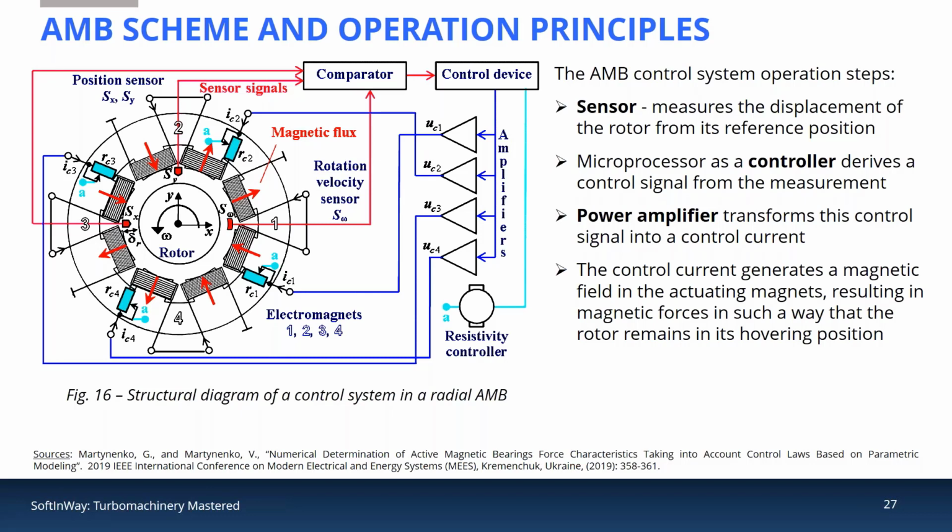The adequate variation of electromagnetic field requires using a certain control law. The control law should be designed properly and ensured by the control system. Magnetic suspension can include permanent magnets if at least one active magnetic bearing is introduced in the system.